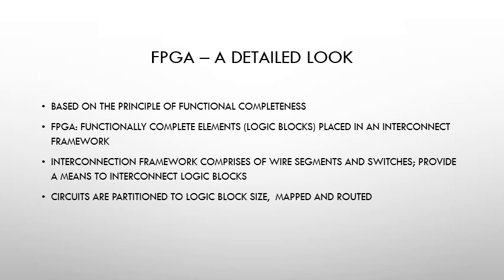Based on the principle of functional completeness, an FPGA has functionally complete elements, logic blocks, placed in an interconnect framework. The interconnection framework comprises wire segments and switches, which provide a means to interconnect logic blocks. Circuits are partitioned to logic block size, mapped and routed.